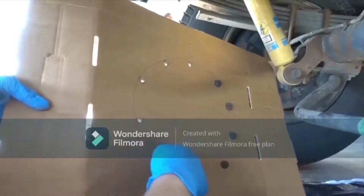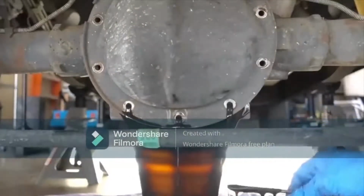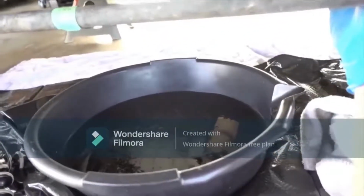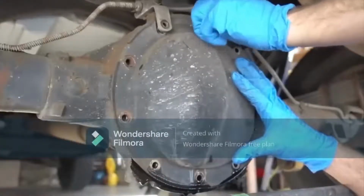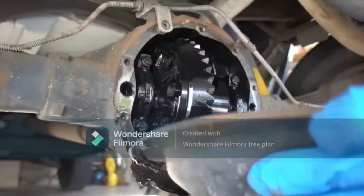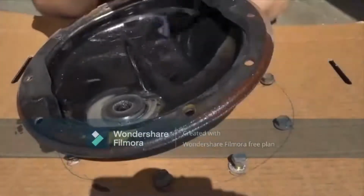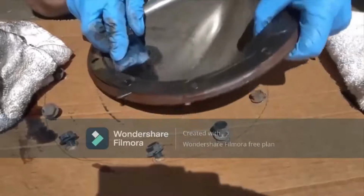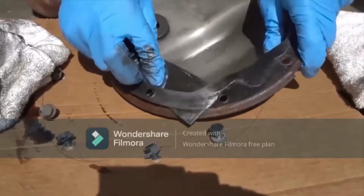Place the bolts on a board or anywhere which can be mapped out to keep track of the amount and location of each bolt. Place a bucket or a bowl under the differential to collect the used differential fluid as it drains for quite some time. Remove the differential cover and wipe it clean using a rag. Using a putty knife, slowly pick the gasket off the differential cover. Do be reminded to avoid any deep cuts to the diff cover.